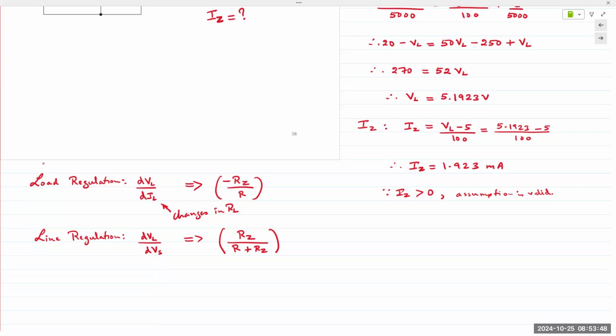Let's say our output requirement is either 5 volts or 7 volts or 9 volts. If our output voltage from the filter capacitor is above 10 volts, we can safely connect a Zener diode and obtain that value, at least safely up to 10 volts. Did all of that make sense? Let me draw it out. Let's do that.